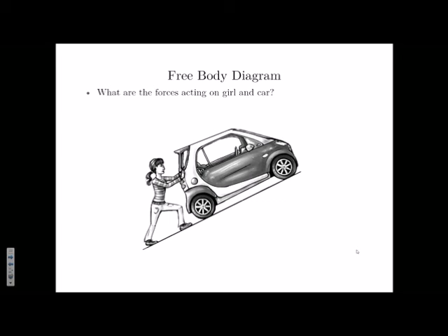If you are only interested in its gross motion, for example, if I said, hey, find out the time it takes for an aircraft to travel from New York to, let's say, New Delhi. Okay? You don't worry about how much the wings are fluttering while it is moving, right? You just regard it as a particle, which has a certain mass. And you apply your kinematics equation to find out how much time it would take for it to get from New York to New Delhi, right? On the other hand, if you're interested in finding out how much the wings really flex while it is going through turbulent weather, because you're trying to design the wing geometry, then you cannot regard it as a particle because you have to take into account the rotation, right?